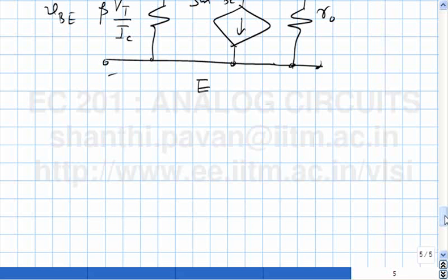And just like what we did for the MOS case, the next step is to derive all the four control sources, where the control parameters, either the voltage gain or the transconductance or the current gain or the transimpedance, are all set by feedback, because when you have a block where the gain is very large but uncontrolled, you can always put it as a forward amplifier in a feedback loop and make the input-output behavior of the feedback system largely independent of the forward amplifier itself.